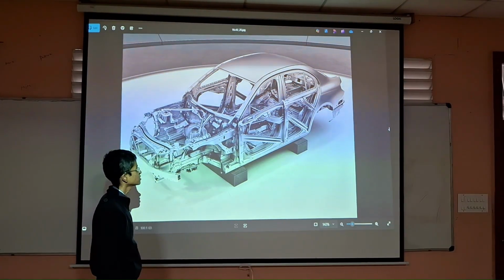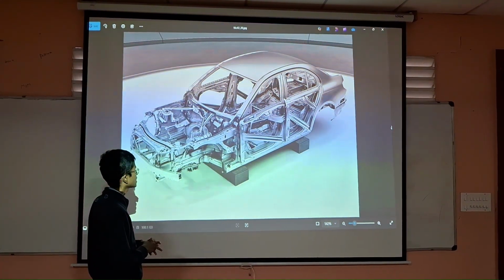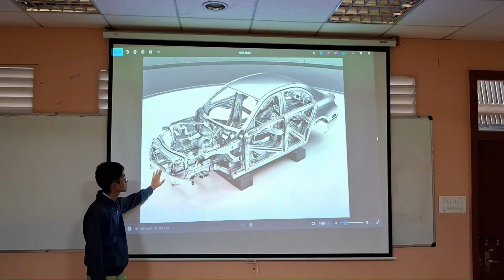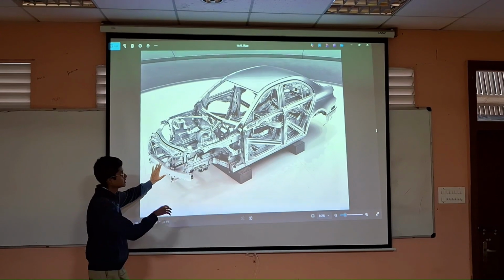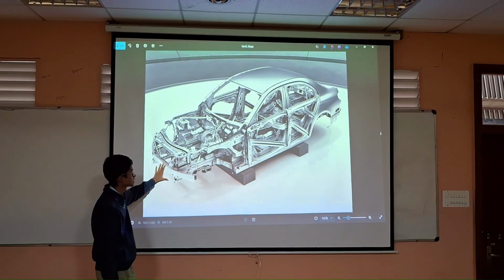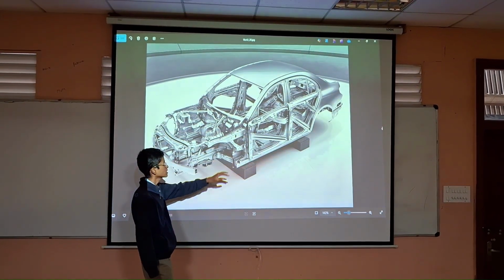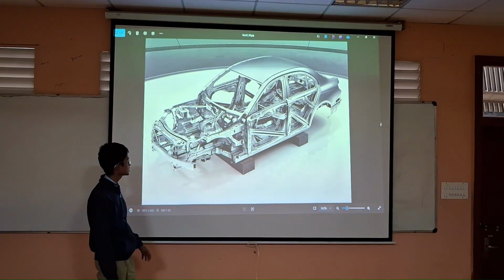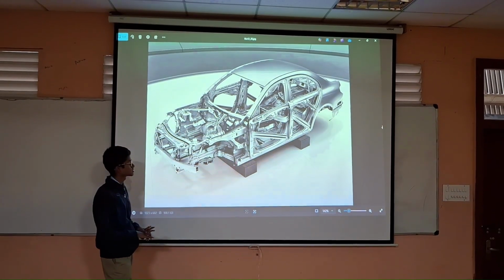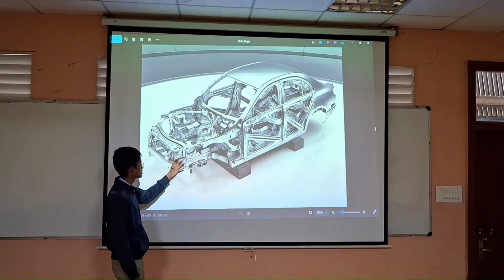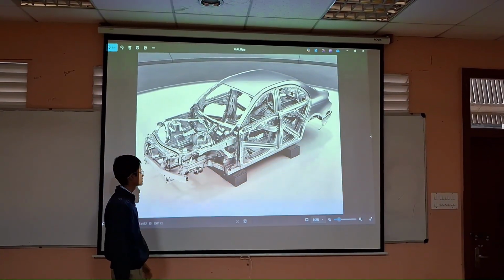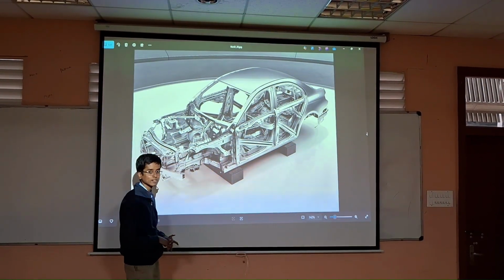Another advantage of this body is better safety. The other disadvantage of monocoque is that heavy pivot loads can't be applied to this chassis because it leads to floor bending and pillar bending. Replacing main components such as the suspension and the engine cradle system takes a longer procedure, and modifying some beams in it leads to a complicated procedure.